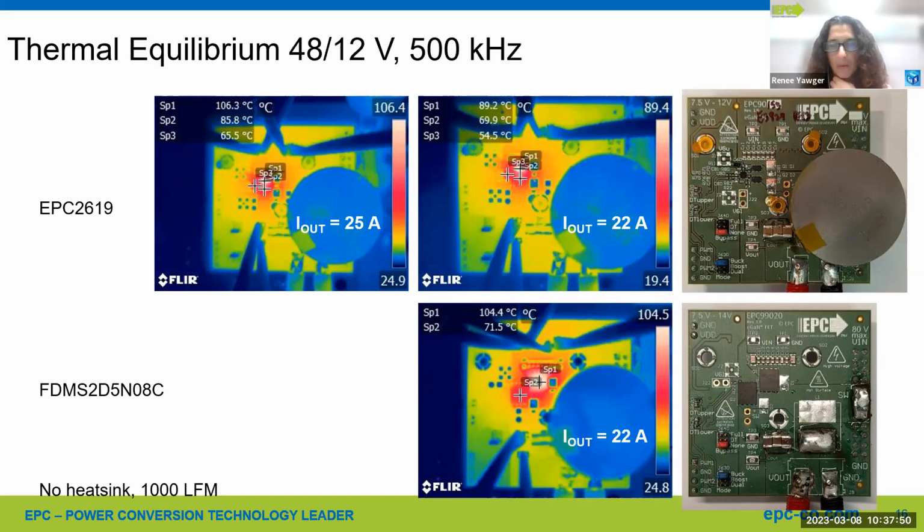With discontinuous converters and high switching speeds, core losses are much higher than resistive losses. Is there any better material or vendor recommended for low core loss when using GaN? We do work actively with manufacturers, and we have reference designs all the way up to 2 megahertz on our website. So I would encourage you to take a look at our high speed DC-DC converters, and there are definitely some inductors there that you can use for these higher frequency applications.